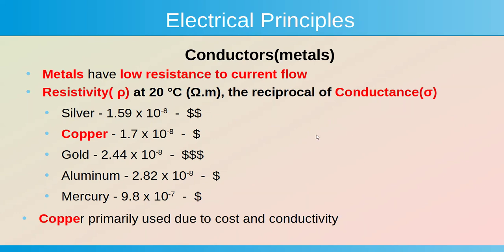Just a tiny bit of trivia, I used to work in circuit plating. Copper and gold are incompatible. So if you need to put gold on the surface, there has to be a layer of nickel between it. And nickel isolates the gold and the copper so that they won't deteriorate each other. And sometimes the cheaper ones, they just nickel plate them.